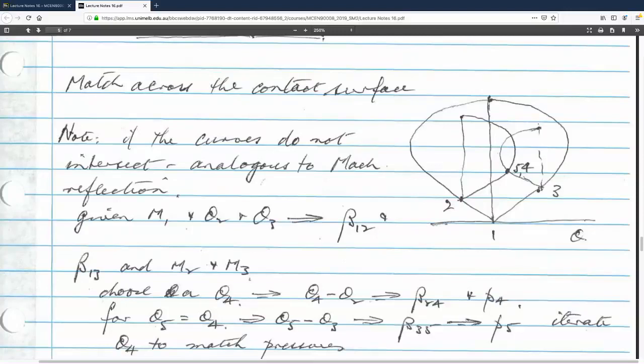Inviscidly, it doesn't make any sense. So the only inviscid solution would be a discontinuity in velocity, a discontinuity in temperature, a discontinuity in Mach number and speed of sound. It's not like the symmetric case. And it's because pressure acts in all directions, so the pressure has to be continuous? Yeah. The pressure has to be continuous across there. It's pretty subtle.